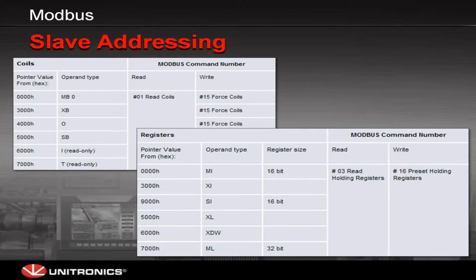And any of the standard series like the 120 or your 200 series or your M90 even, the older ones, use different slave addressing tables, but in our help file is where I grabbed this information from. So the Enhanced Series controllers, the color screens, do have different addressing schemes than the standards, but it's all published in the help file if you wanted to reference back to those again.